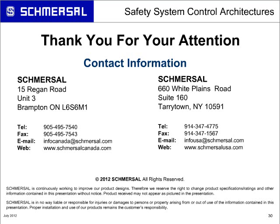EN 954 revolved around control categories, and it kind of stopped there. But over the years, what everybody has learned is there's more than just how something's wired. It's also the hardware reliability and the overall design of the safety system and your possibility of failures occurring. So the control categories are what's referred to as your deterministic approach, where you're determining how your machine or your safety circuit in particular is going to function.